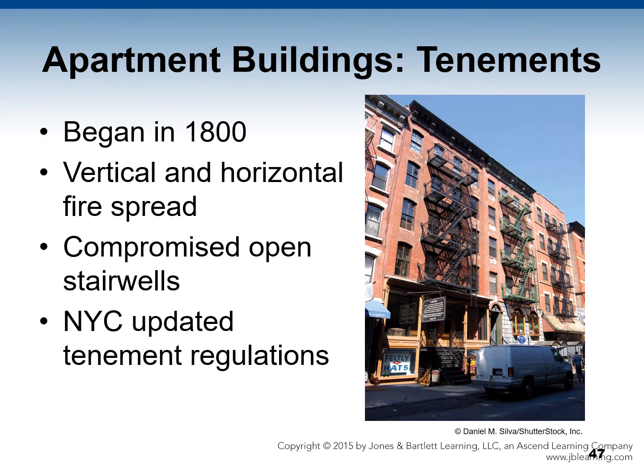Vertical fire will spread through voids, and a horizontal fire spread will go through the cocklofts, and compromise is always present in open stairwells. You also have fire spread via shafts. Sometimes these have elevators in them, and air shafts, etc. New York City updated tenement regulations in response to devastating fires. And if you do a little bit of research, you'll see some horrific tenement fires that occurred in the city through the generations. So now the standards require better enclosures of stairwells, more substantial apartment doors, exterior fire escapes.